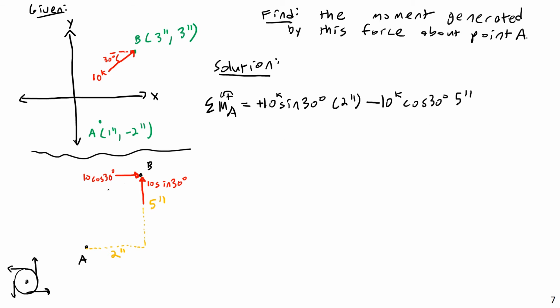And again, the reason I made this term negative was because the x component here is rotating clockwise about point A. That's like a positive moment there, or positive rotation. And negative rotation, if you think about velocity vectors around that, negative rotation is clockwise, and the velocity vectors look like this.